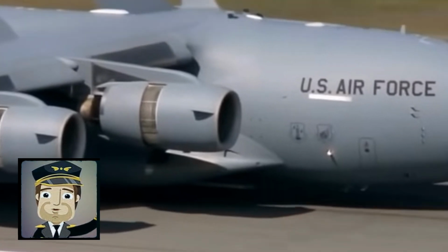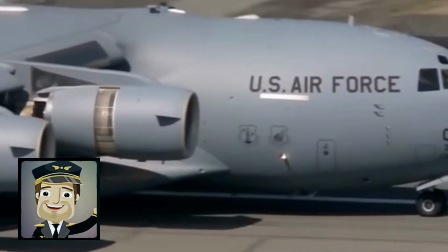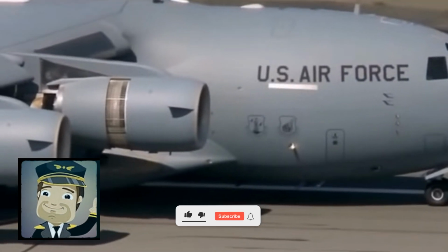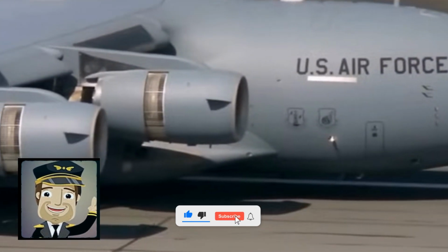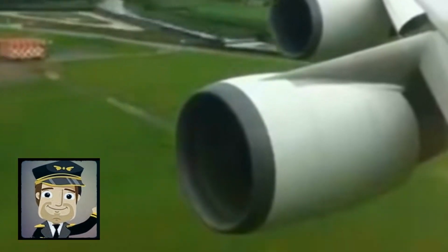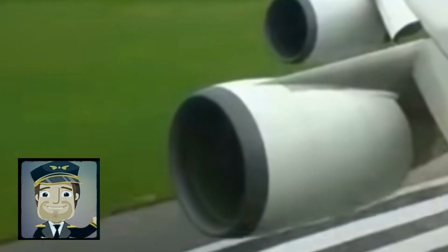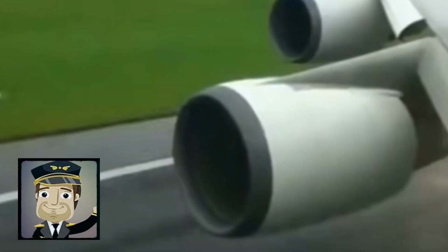Thrust reverser maintenance is critical for operational safety. Regular visual and functional inspections are carried out to verify the condition of hinges, actuators, sensors, and moving panels. A malfunction in the system can result in asymmetric reverse thrust, causing the aircraft to veer off course on the runway, which requires immediate correction.